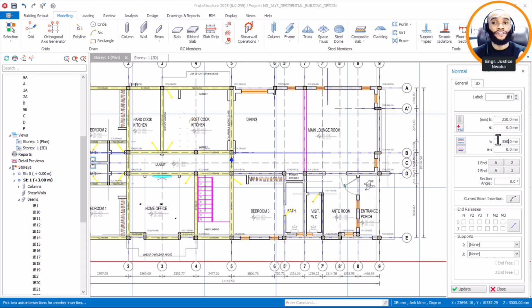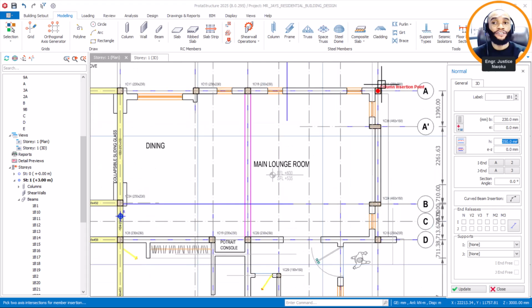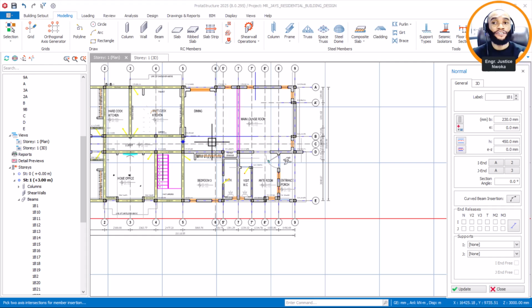So the same thing, we cannot use 350 here, all right, because you have to calculate your depth. Although this thing can still work structurally, since the concrete section now becomes small, the whole load is going to go to the steel, and in that case it will make the reinforcement bigger, or having so many numbers. Okay, so with that now, let's still maintain a beam depth of 450. Okay, that's fine. But our slab around this beam area will not be 150, it will be 120. Okay, that's fine.